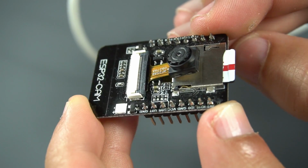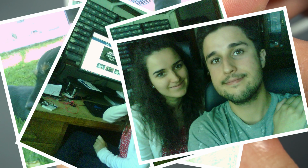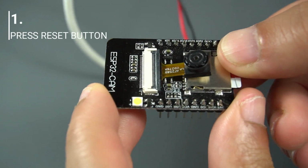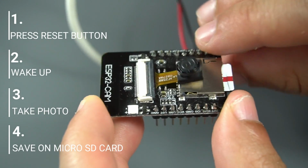In this video, I'm going to show you how to take photos with a ESP32-CAM board and save them in a microSD card using Arduino IDE. When you press the ESP32-CAM reset button, it wakes up, takes a photo and saves it in the microSD card.